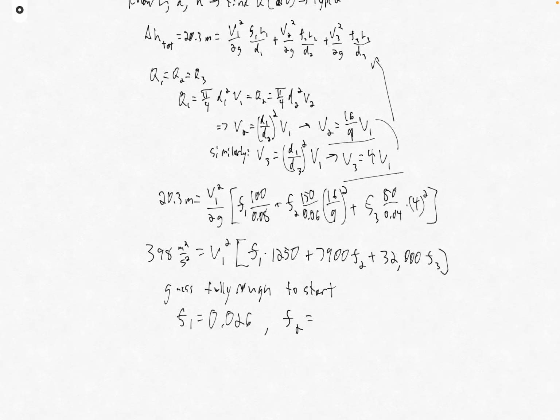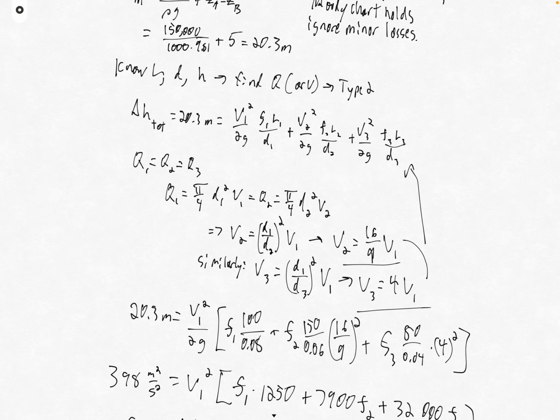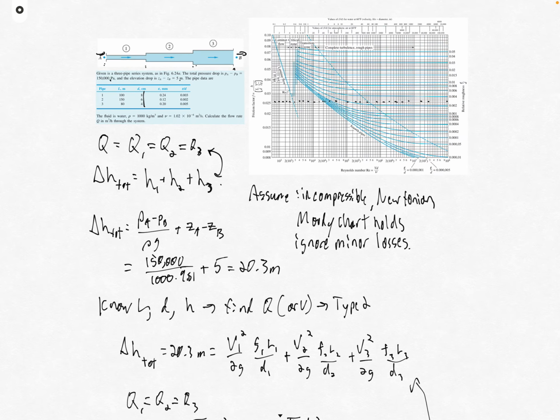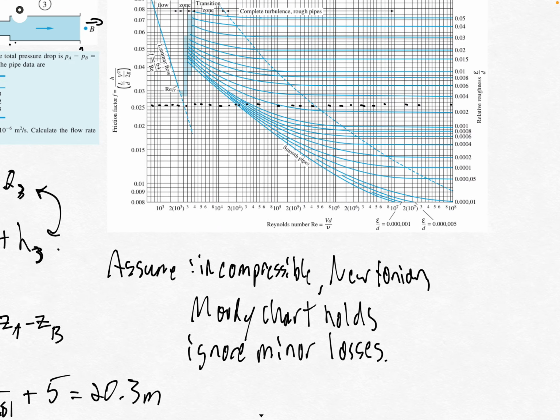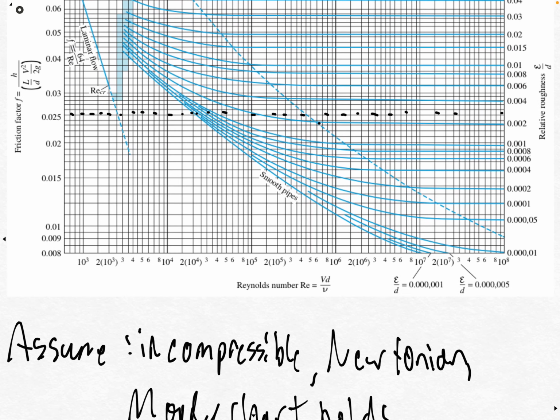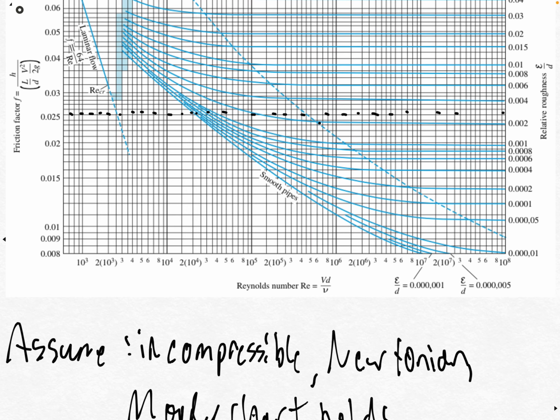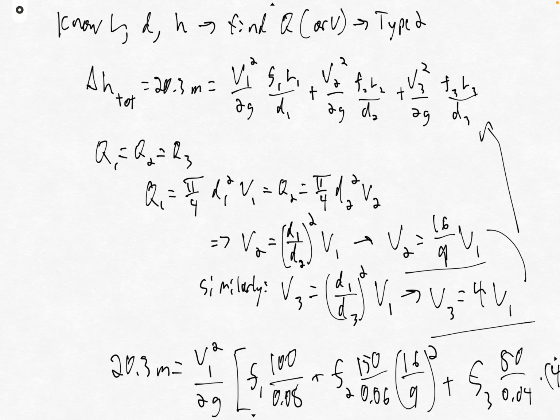f2, so again, we have a different roughness here, 0.002. If we look at that fully rough value, just to say right at that boundary there, let's just double check that. So this is 0.29, 0.28, 0.27, 0.26. Oh, sorry, that value is 0.025. f1.